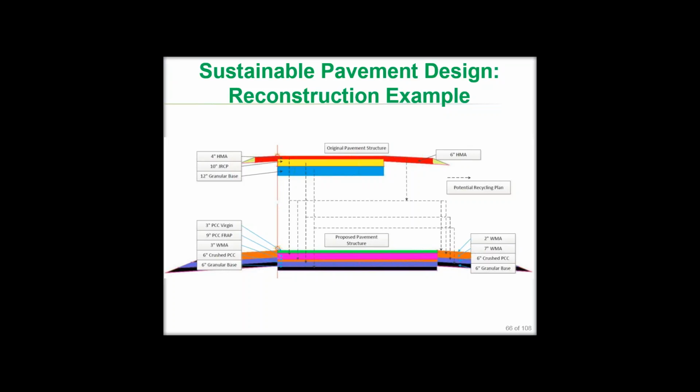It depends on whether this is an urban area or a rural area, but one has to carefully think, in the design stage, about how one can build the layers in such a way that you're going to minimize the energy used to build this new pavement structure. And setting up staging areas and helping with mobile processing are going to be ways to reduce the energy costs.